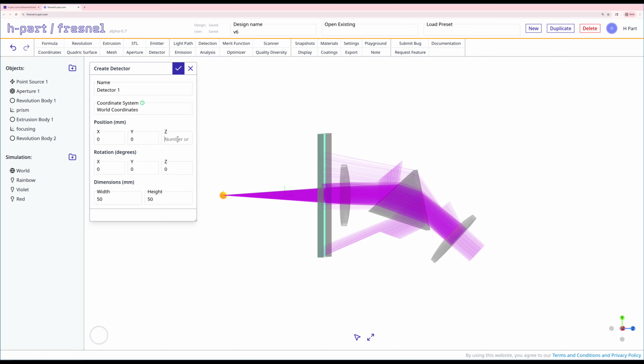As I mentioned, we want to create this detector pretty far away so that we give the slight angular differences the prism creates enough time to be turned into reasonably large position differences on the surface of the detector. And in real life, this detector would probably be a line scan camera or a regular camera. So we want to space it out so we can improve our resolution.